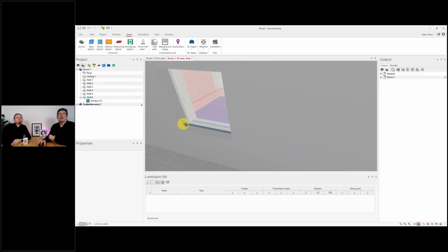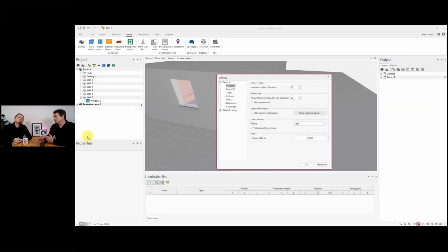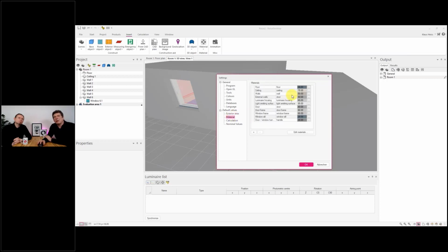At the moment, it is only possible to have one thickness of the wall globally per room. All rooms. Yes. So let me switch this a little bit back. It doesn't matter. If you change here just, then you will just affect the active scene. If you save as default, it will be stored also for new projects.